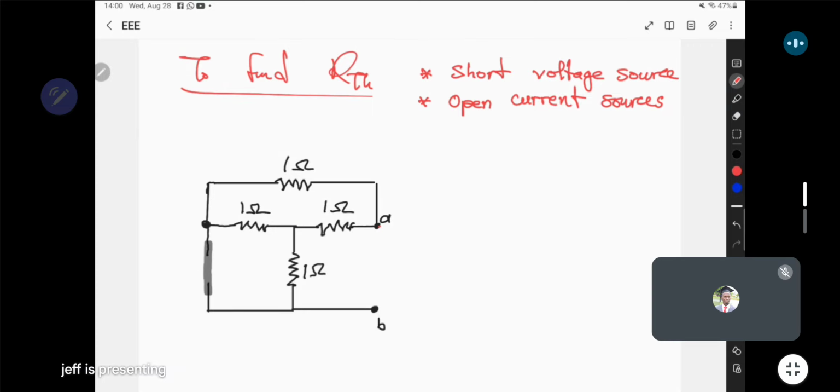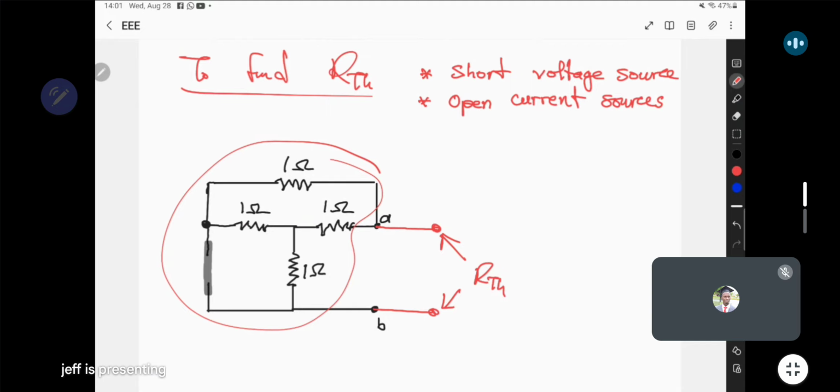Once we have done that, you want to find the equivalent resistance viewed from the points where the load was connected. So this is what we're going to do. It looks weird when you look at it like this. To make it clearer, look at point A as if it was a node like this. It makes it clearer that you're finding the total resistance viewed from here, meaning everything else here must be presented as one thing. So how do we find the total resistance?